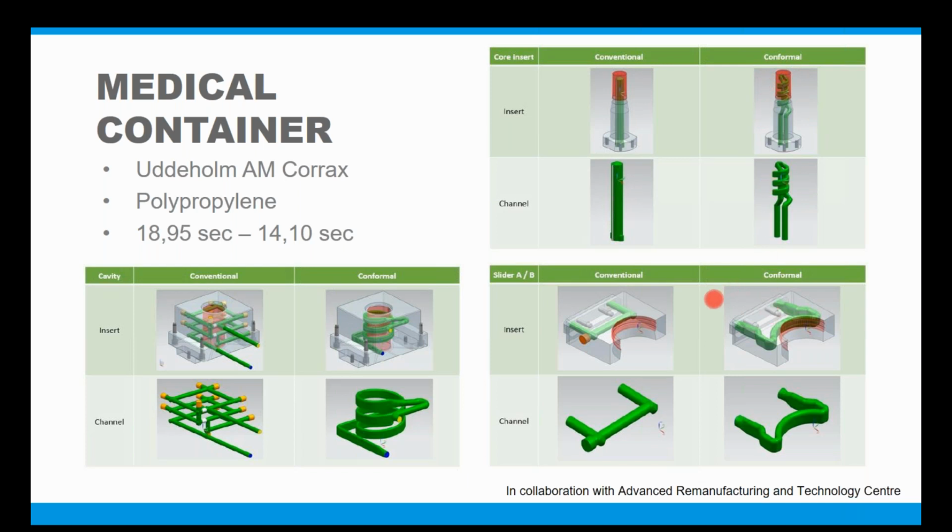But these moving sliders are also really important because here the plastic is much thicker than in the rest of the container. So I would recommend to print these two and probably not print this one, because you can see there's a lot of mass right here, so this is quite expensive to print.